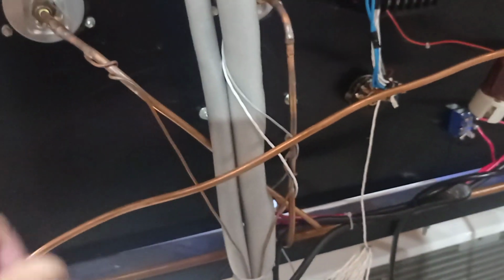This is a humidifier switch through which we'll connect the humidifier like this. To connect the humidifier, the rest are all connections of the LPHP cutout through the capillary. One thing I want to mention is that the expansion valve used is a capillary valve. The capillary valve is used to cool the refrigerant to low pressure, converting high pressure to low pressure.